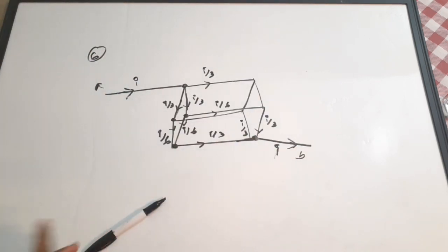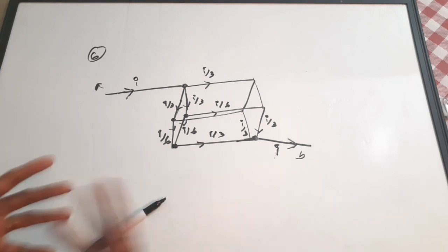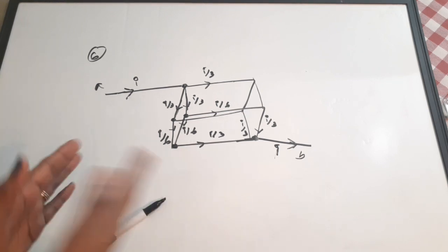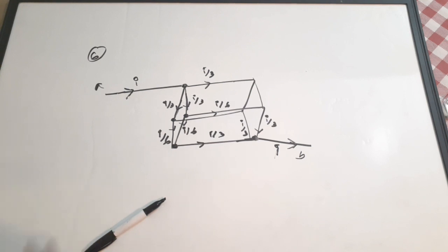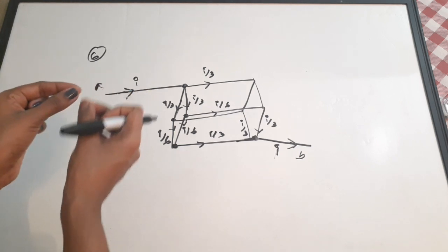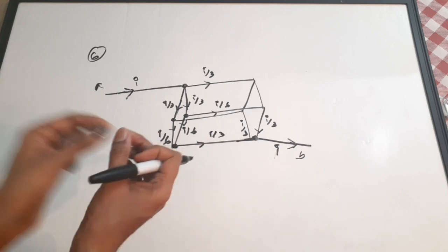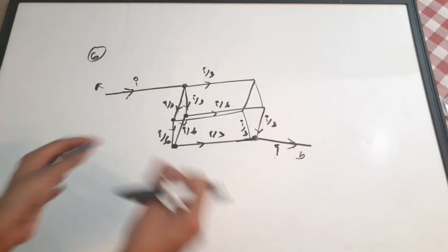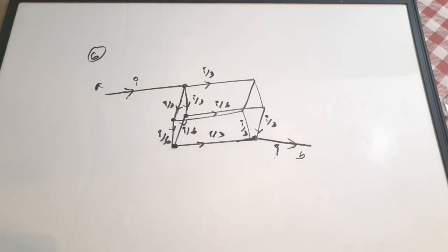That's a concept. Even though I'm saying applying KVL along the diagonal, you can only apply KVL along a loop or a mesh. Most commonly, we only do that. So, just consider that you're taking all the resistors connected between the two diagonal points, combining them and forming a loop, and then applying the KVL.